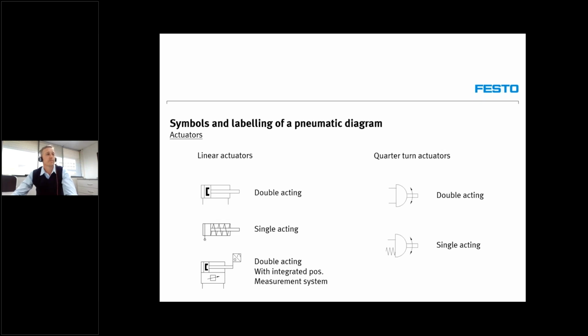Yeah, where I was going with the question to Sky earlier on is we have basic devices, not just Festo, but companies like Festo, basic devices available off the shelf that monitor air consumption and flow and pressure on a continual basis that can be logged to a PLC. So it can be time stamped and logged to a PLC. So you get an exact indication of what your consumption should be, and perhaps the desired conditions, like a good installation. And then, of course, based on the benchmark, you get feedback about the consumption. So as soon as you see a deviation, of course, you can take the respective action.